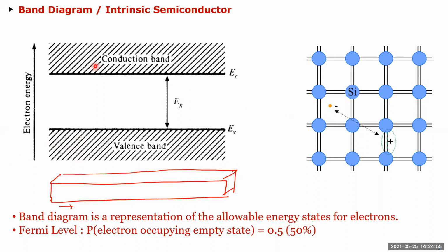And that's what the energy band diagrams capture. Basically, they tell you the electron energy, and for this particular material, what the available states are within these energy levels, and that tells you if something is going to conduct or not conduct.